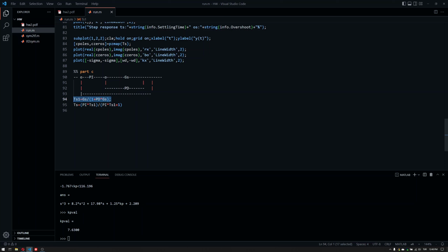You will have KD and KP parameters in your denominator. Once you complete the whole thing with another loop using the PI controller, you will get the zero of the PI controller. T(s) has no zero, and you will end up with the same characteristic polynomial in the denominator of the closed loop.